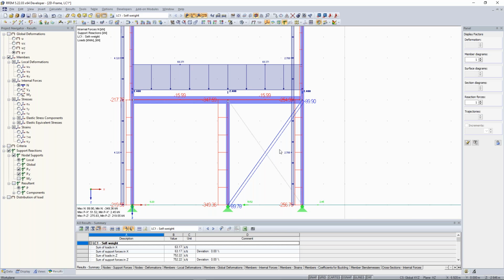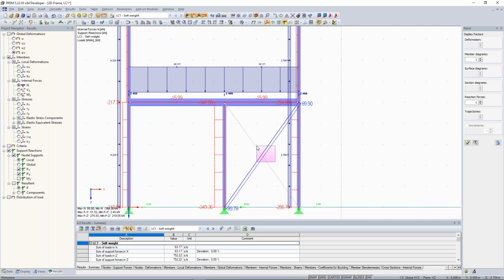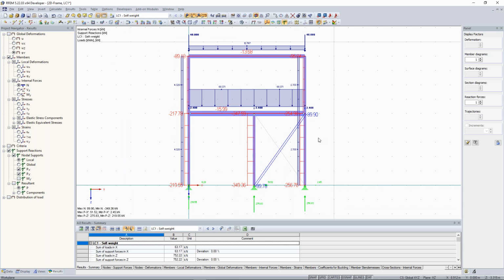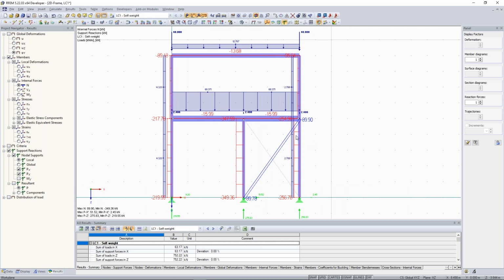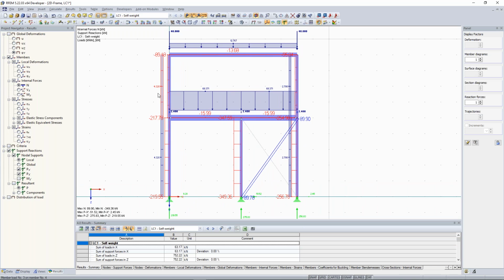And that's also the reason why in reality all buildings get bracings on both sides. So I have here this bracing and then I have here this bracing, yeah. So this bracing on that side and this bracing from that side. That's because you don't know on which side the wind loads, especially the wind loads, are coming from, yeah. In this case, we make it very easy.